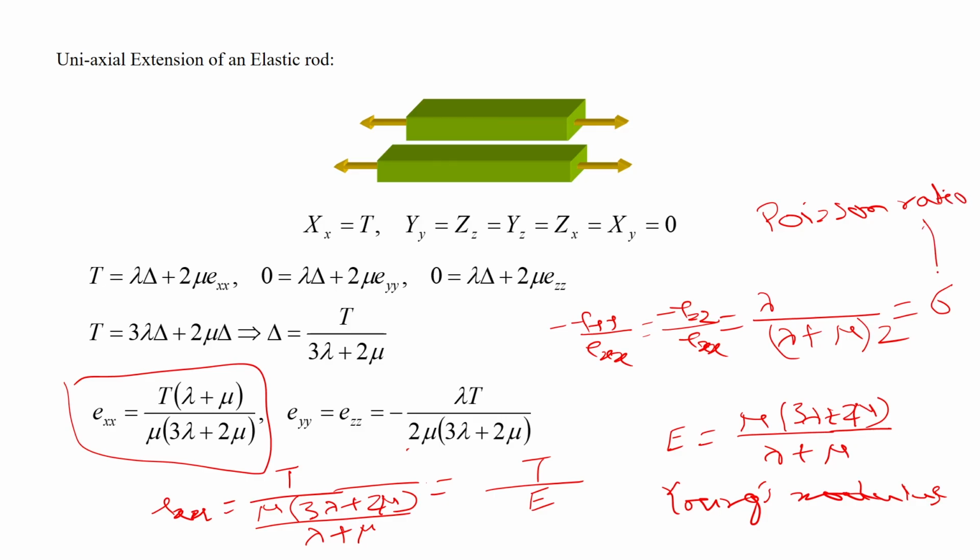So, Poisson ratio defines the strain that, if you give a body uniaxial strain, so you have a given body, this is Exx, and because of the stretching in one direction, there is strain in the other directions, Eyy and also Ezz. And so, the ratio of these strains, Eyy by Exx or Ezz by Exx, is given by what is known as the Poisson ratio, and Poisson ratio is represented by the notation sigma,